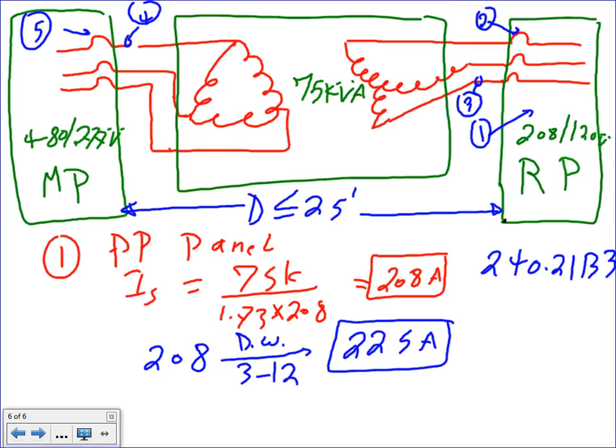And the reason why I bring up the bus size is that when you do estimation and the project is very expensive, you need to do so-called engineering design. You go back and say, well, we went up on this panel, we could go down to make the project affordable for the customer. If you don't know the actual panel size versus the overcurrent device, you can't do that. So anyway, 225, that's the panel size.